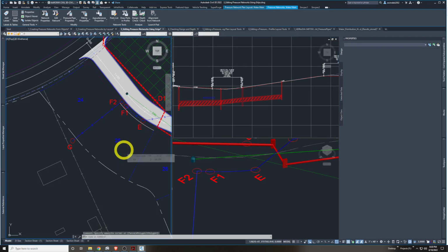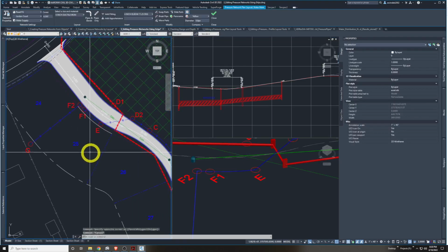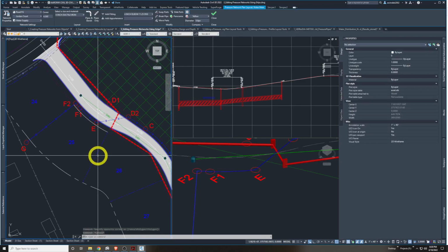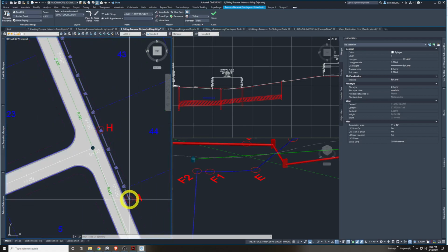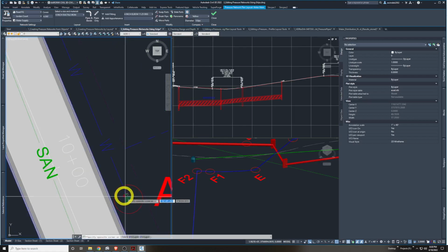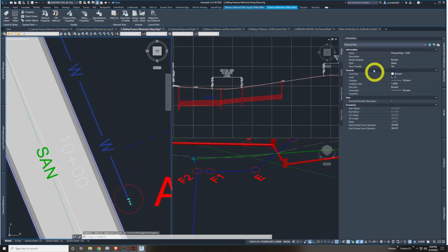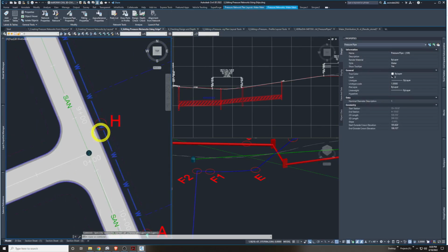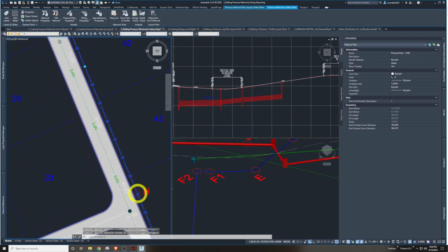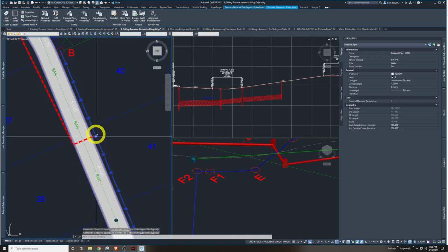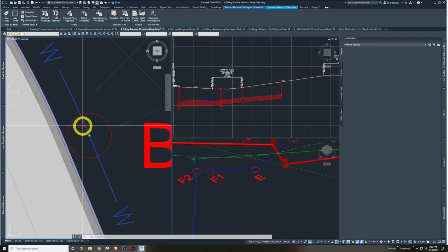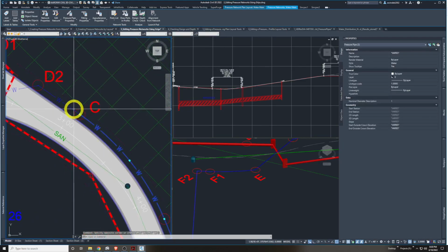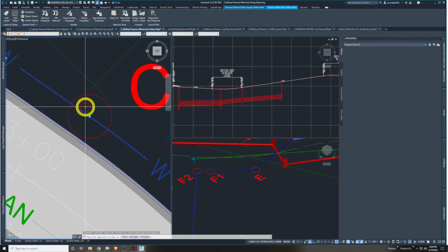Let's go back to this viewport, hit escape again, but now let's start picking more pipes, all pipes and fittings basically from circle E to A. So let's start at A. Let me use a cross box in that method. Looks like I got everything there. If I miss something, it's not the end of the world, but I'm going to cross box in this direction in the negative. So grab stuff, same here.